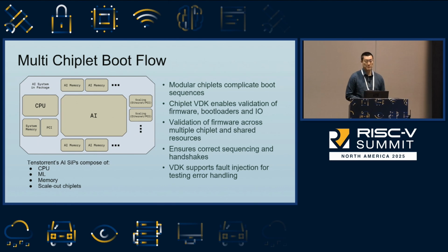While chiplet technology promises numerous advantages, its modular nature complicates boot sequences, particularly in terms of interoperability, testing, and debugging, which can impede the overall system verification. A chiplet VDK built using Synopsys Virtualizer model libraries offers a solution by enabling early development and validation of firmware, bootloaders, and I/O protocol stacks. It facilitates testing firmware interactions across multiple chiplets and shared resources, ensuring correct sequencing and handshakes during chiplet initialization and boot.